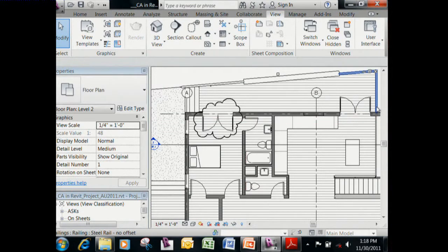So if you were to cloud it in the sheet, they may not necessarily show up, especially if you're duplicating a view with annotations and they're creating it in a sketch format. They wouldn't carry along. But I think the important thing is to establish a strategy and discuss it with your team and remain consistent, because the worst thing is when you have some clouds in views and some in paper space, and it's a mess. You are going to end up with some in paper space if you make any changes to your title block, if you were to, say, change the number of the sheet.